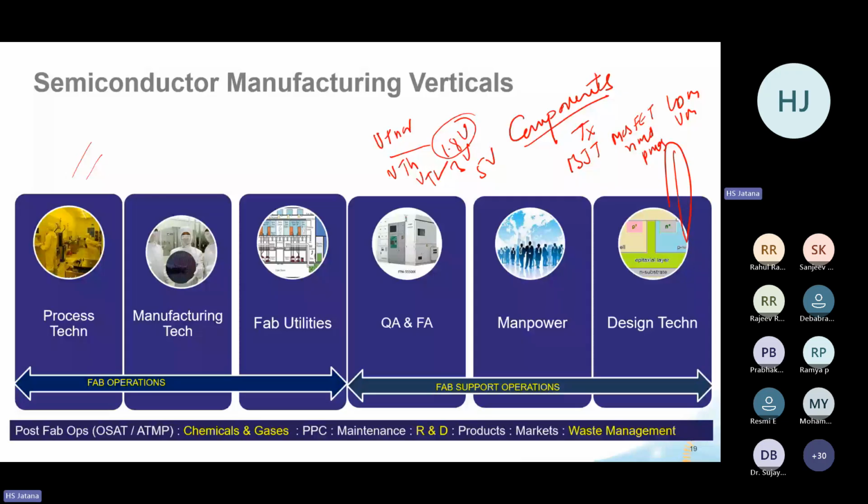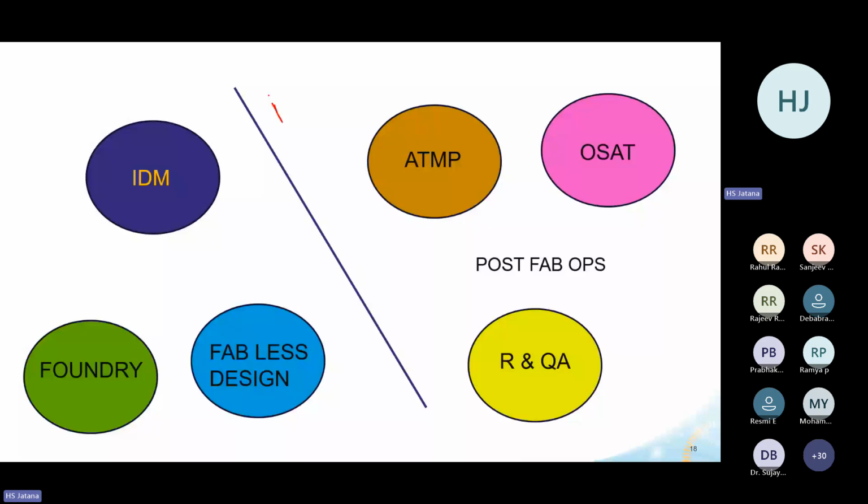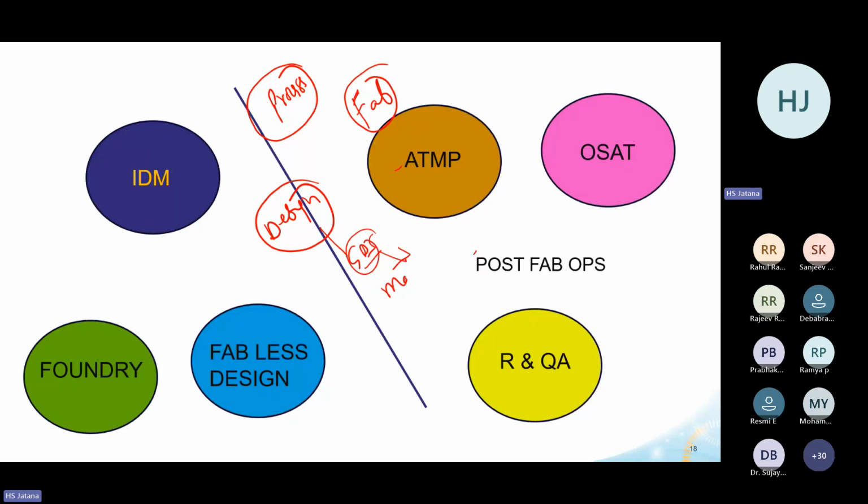Now, you see, these three things are related. One is the process, people who will design the process. Designers, they will do the circuit design. Now the circuit design people will release the design in terms of a GDS tape, which has information about all the layers. That will go to the mask engineer. The mask people have to make masks, and the GDS will be changed. There are some optical corrections, OPCs. There are resolution enhancement techniques based on the litho.